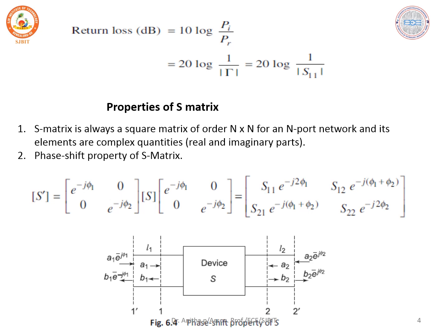Or you can express this in terms of A1 square divided by B1 square. So 20 log A1 by B1. A1 by B1, again you divide numerator and denominator by A1. So 1 divided by B1 by A1. B1 by A1 is nothing but S11. So 20 log S11. S11 is nothing but the reflection coefficient K at port 1. So this is about the different types of losses which usually occur in a two-port network or in a microwave device or microwave network.